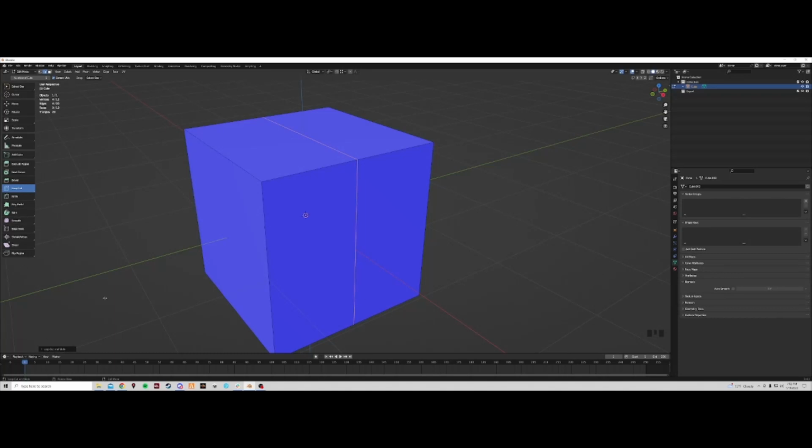down here, and this is with all tools, pretty much everything you do in here will have a small little box that pops up. And these are different settings you can change for what you just did. I just created a cut, so I have loop cut and slide setting. I can change the number of cuts right now, and it will evenly place them for me.